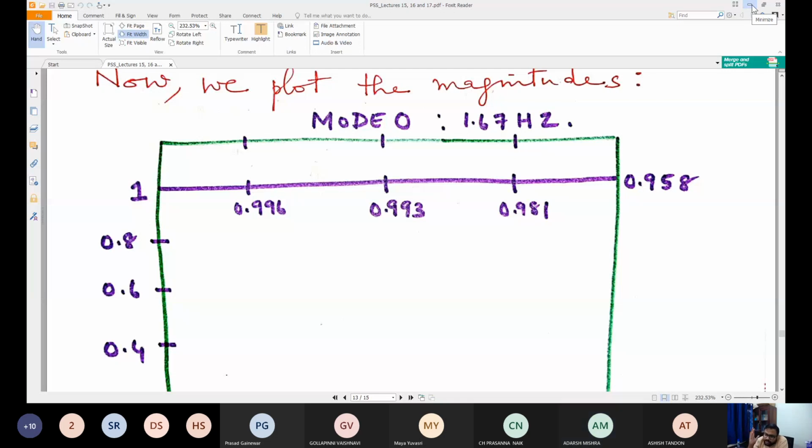According to the direction of the tie line power, one region may be generating more power, and if there is a deficit, we can pump it to the other control area. That is the whole purpose of having a tie line. But what about the frequencies of the control areas? Delta F can be different in both the control areas. The change in frequencies can be different in both the control areas.